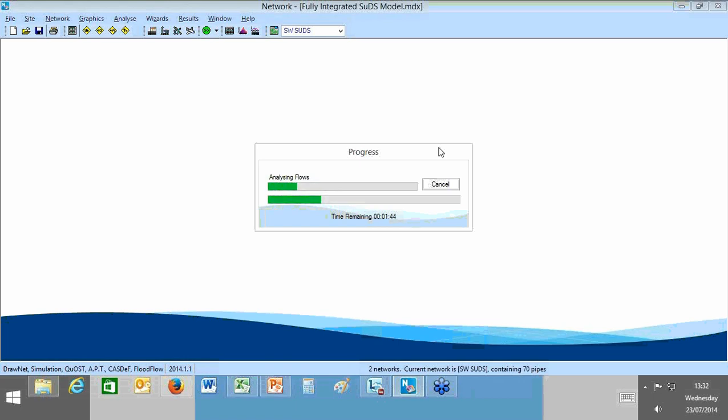With the apply rainfall directly onto the grid itself, it has the same effect. The runoff that's generated on the surface will then be enabled to flow into the underground network through those 4 gully entries. And then if the flooding came out across the surface, it would be allowed to re-enter as well. So I've chosen the static because, as I say, this is the worst case scenario. The flooding is coming out at various manhole locations.